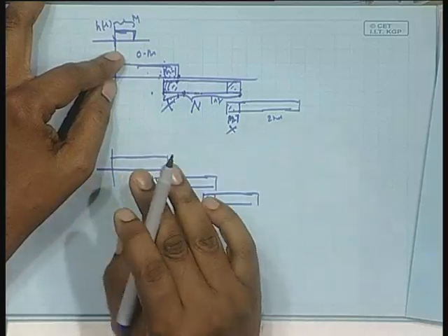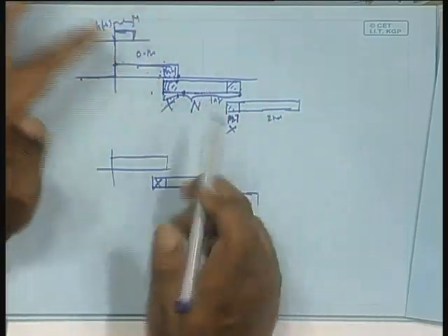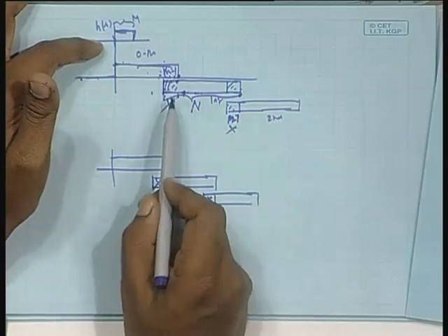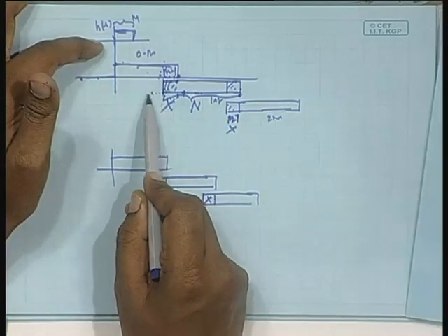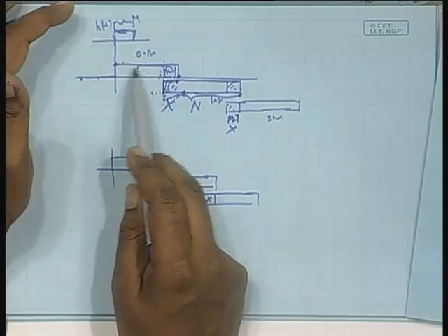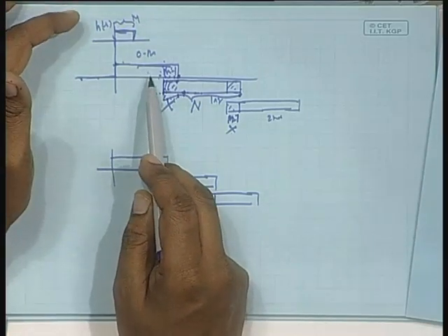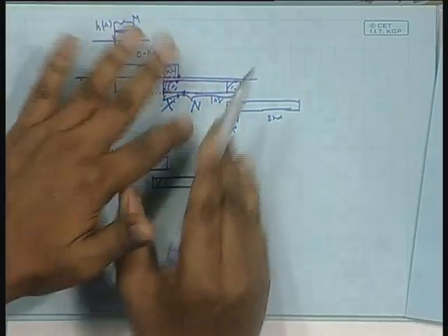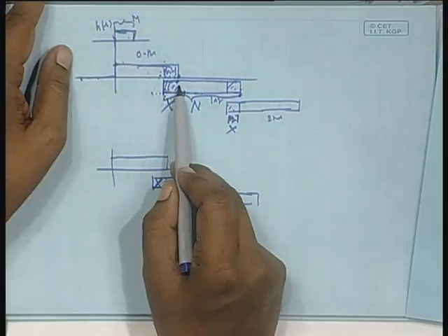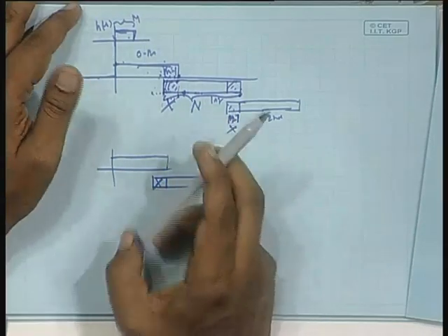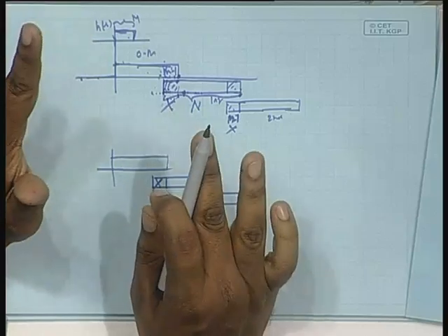But before that, let us carry out the convolution between the two. Only the first M minus 1 samples are wrong, we know, because they assume 0 values to the left, whereas actually there is data, and they assume the same filter weight, or the filter weight has changed, and I am putting back the correct one. But even then, first we calculate the linear convolution, and only then will I throw away this part, is it not?